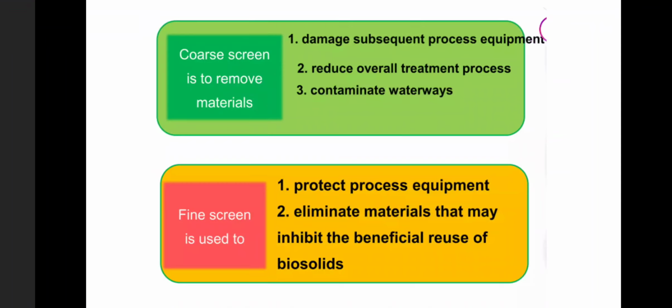This bar rack further protects against the entry of floatable particles into the treatment system. Coming to the continuous belt screens, a guide track is provided, and before the guide track, an influent cover guard is provided. So there is a two-step protection against the entry of particles.